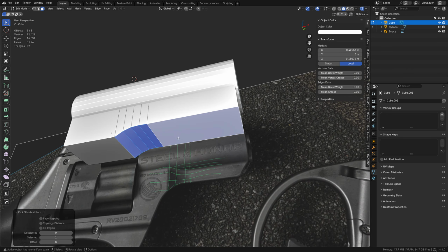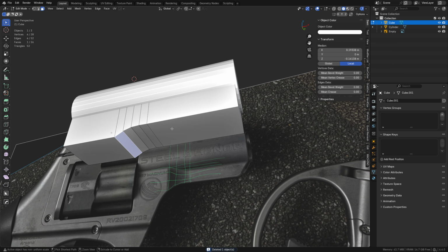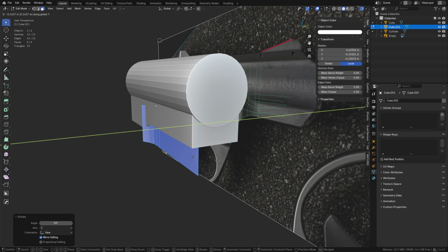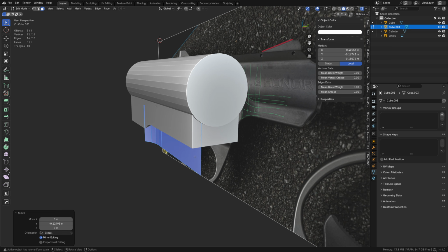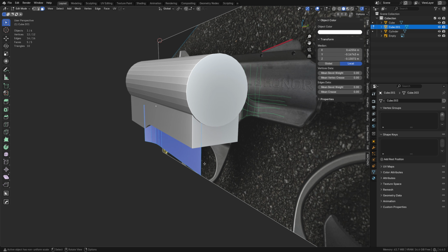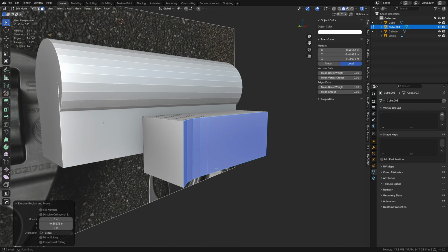I'm actually going to steal this geometry down here. Usually you Shift D, you duplicate, right click P, separate selection. And then you go to object mode, select it, and then you have that piece, right? Machine tools makes this much easier. Just hit 4, right? And we can rotate that. I think it's going to do something like this, right? I'm just going to extrude it out, not rotate it. Okay. I guess extrusion was acting weird. There we go.